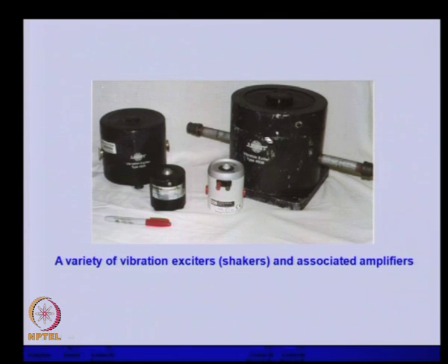So, with this we can excite the machinery externally, and we can choose either the frequency of excitation or the amplitude, or even what kind of excitation force we want to give, like sinusoidal or two frequency signal or multiple frequency signal or random signal. So, depending upon the application we can excite, and then we can measure the corresponding change in the vibration, which can be used to find the condition of the machine.